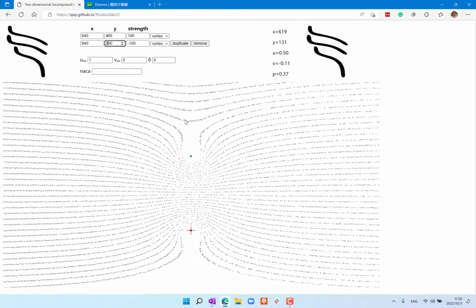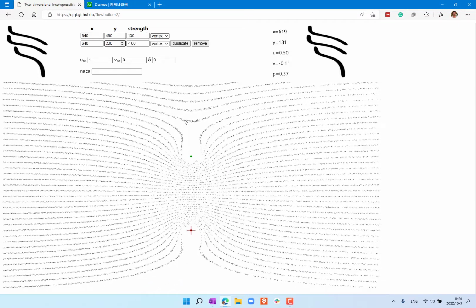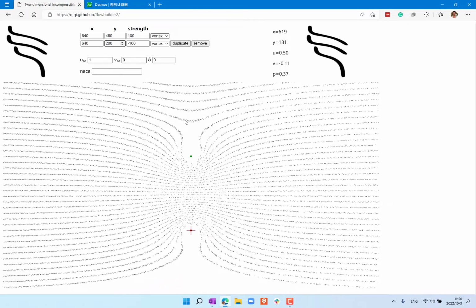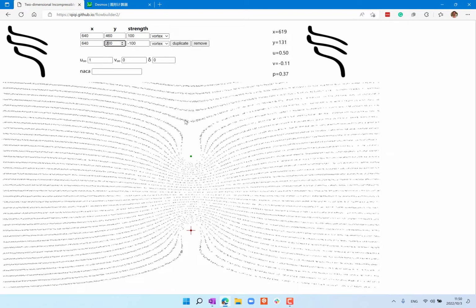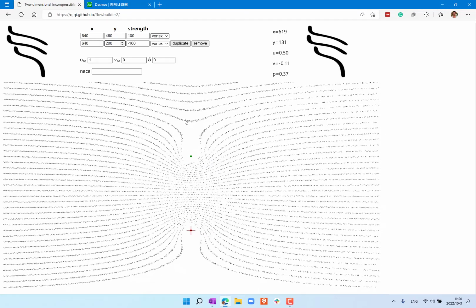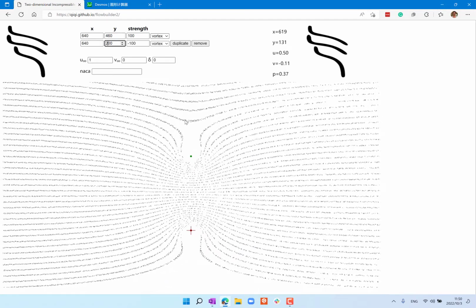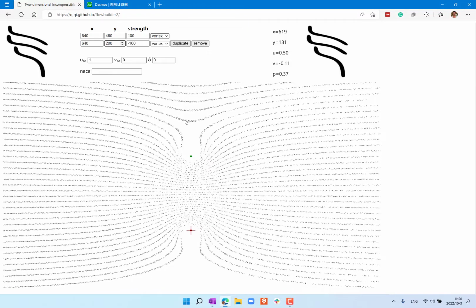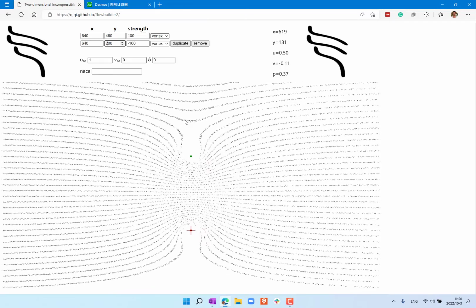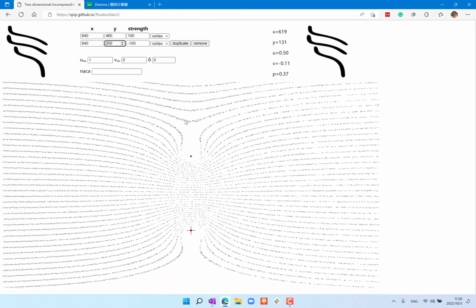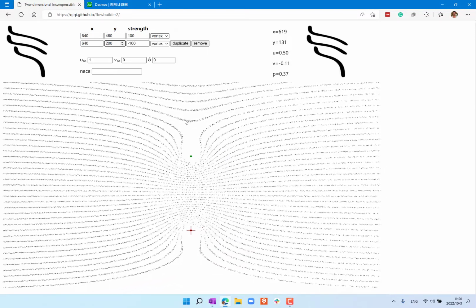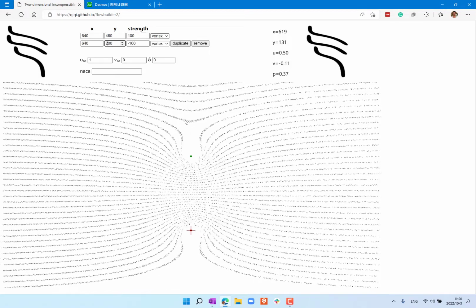Now, what does that mean? What force provides the force needed for that upwards acceleration? Pressure gradient. That's the only force in the inviscid flow field, right? So that means at this point, is the pressure higher above or higher below? Higher below, right? How about this point when the flow is curving downward? It's higher above, right? So that means the pressure along this line is highest at the center and lowest towards the vortices.